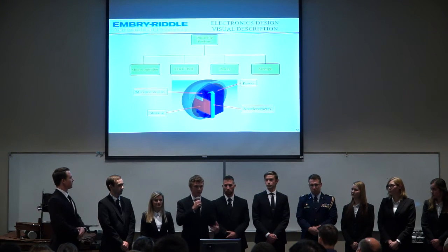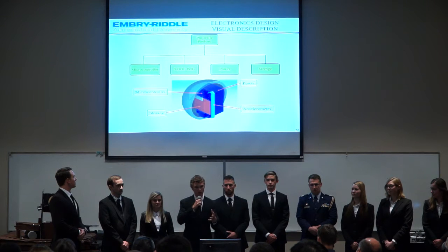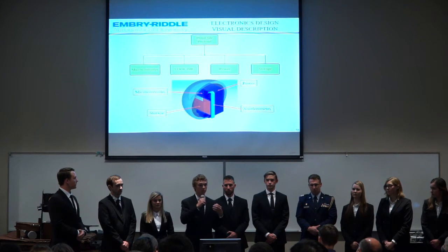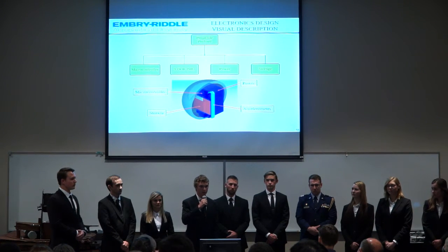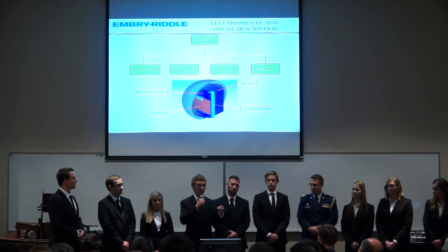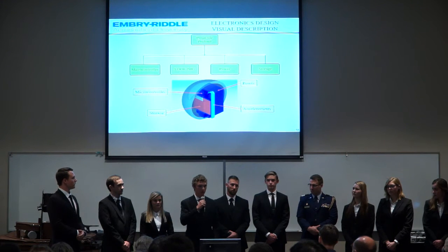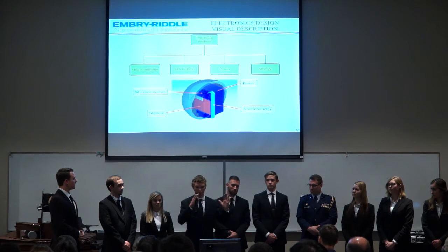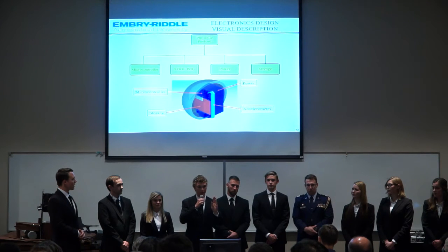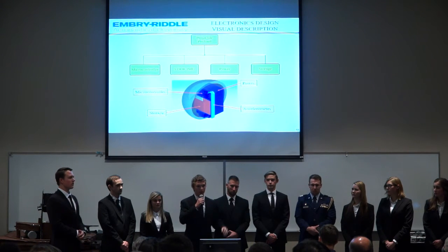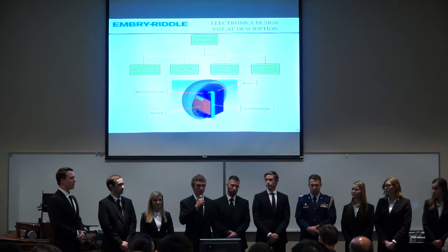So the current plan for mounting those inside, what is not shown in this CATIA figure is that there will also be lead shot epoxy inside of the projectile payload. This is in order to pull the center of gravity forward of the center of the projectile and give us a little bit of stability, as well as increase our ballistic coefficient. So that will enclose those a little bit more, and then from there we are planning on sticking foam in between there in order to encase those electronics even further and keep them safe during impact. Okay.